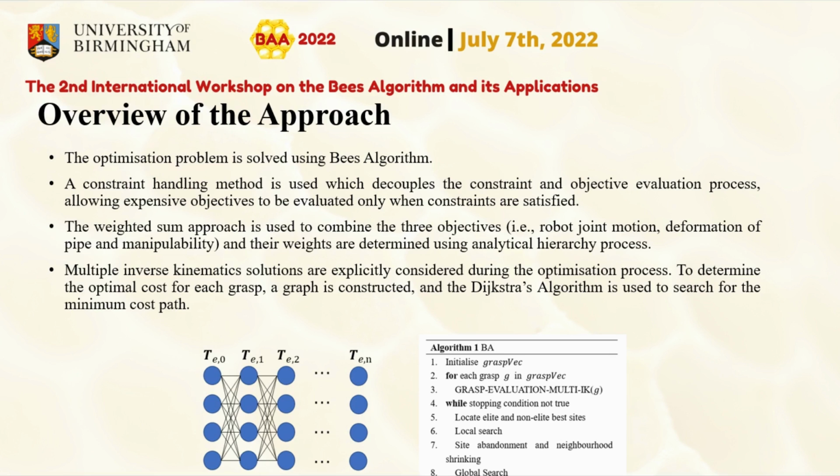You may have already noticed that we said we want to optimize both grasp pose and the joint motion, but we only use grasp pose as decision variables. This is because each grasp pose usually has a finite number of inverse kinematic solutions for a non-redundant robot. Therefore, the problem of optimizing joint motion becomes solving the inverse kinematics problem followed by a shortest path search on the robot configuration graph, just like the figure here.